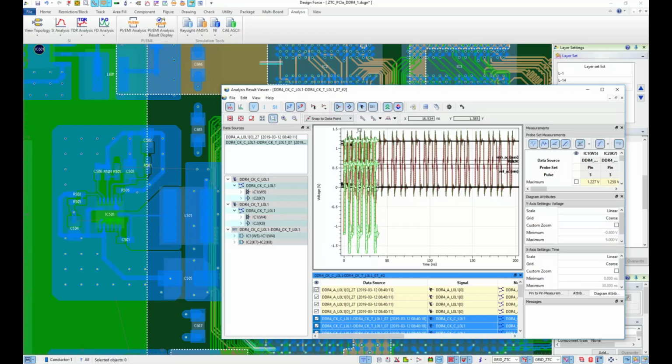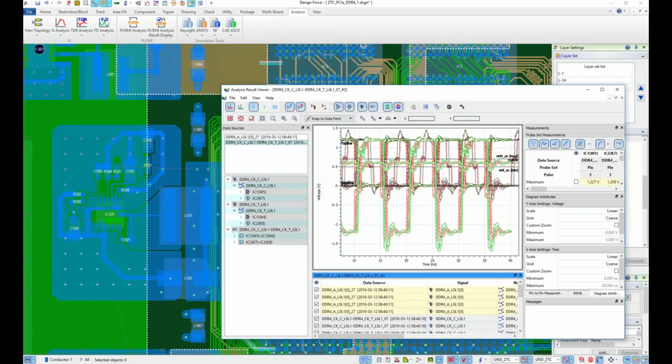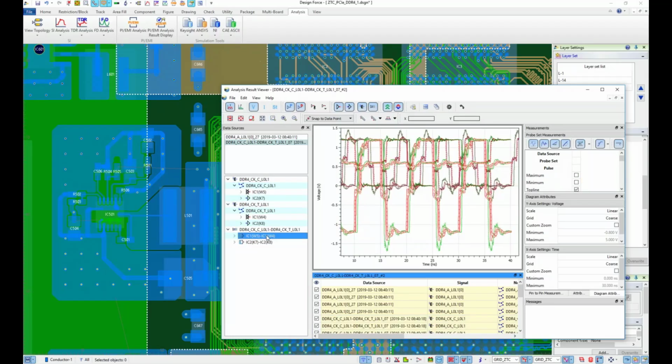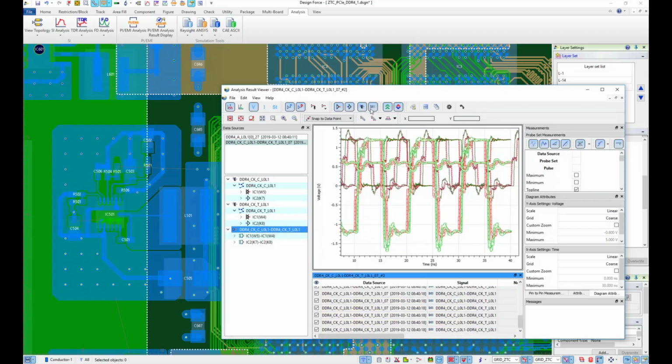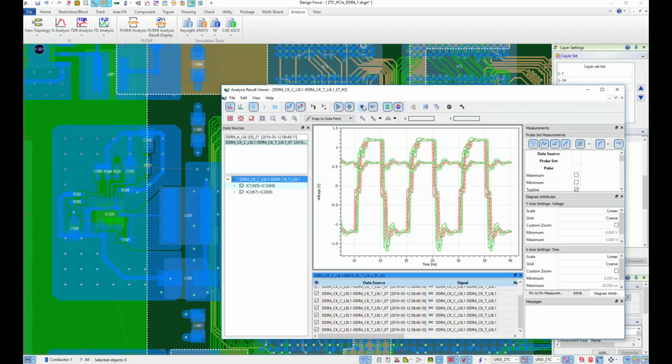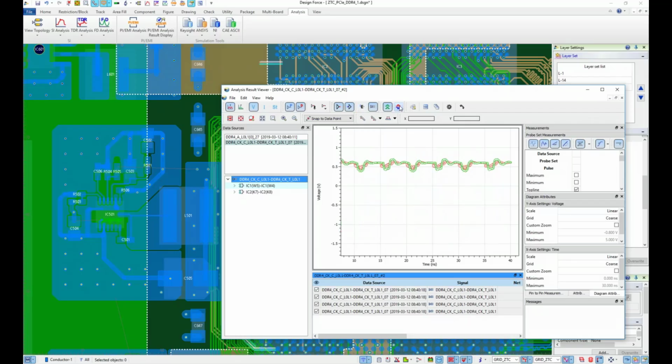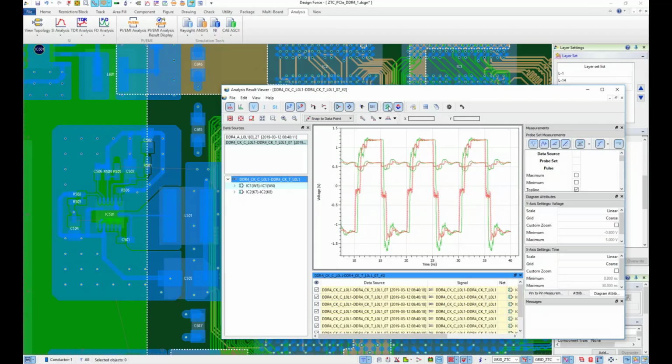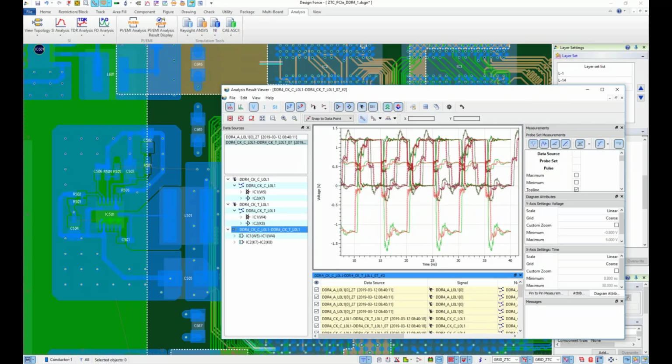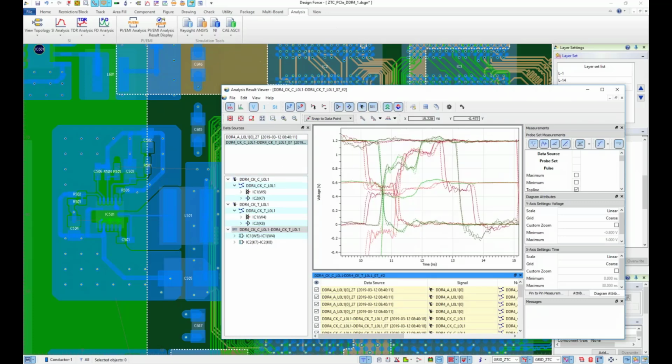And here I do have now my simulation result for my differential clock. I just look into the differential signal. I do have my common mode voltage and I do have my differential voltage. So you can do any kind of dedicated analysis, how signals are operating in relation to each other, taking into account the true interconnect timing behavior on the driver and the receiver waveforms here.